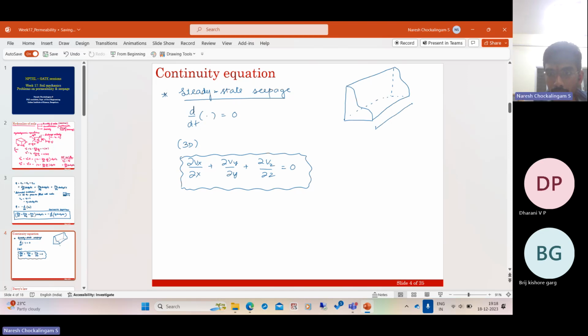So if the length into the plane of the dam is say L, and the dimensions in plane are say dx and dz, usually dx and dz are much less than the length. And say the dam is supporting a water table on this side. This length is very long, so you can assume things to be under planar flow.